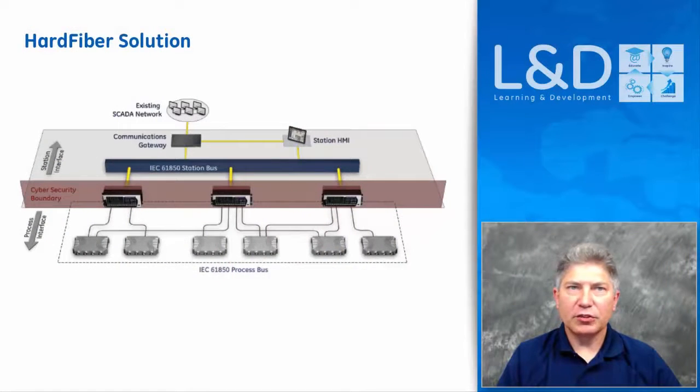The HardFiber system uses IEC 61850 to communicate measurements and commands between bricks and relays in the control building over dedicated point-to-point fiber optic connections that avoid cybersecurity issues altogether.